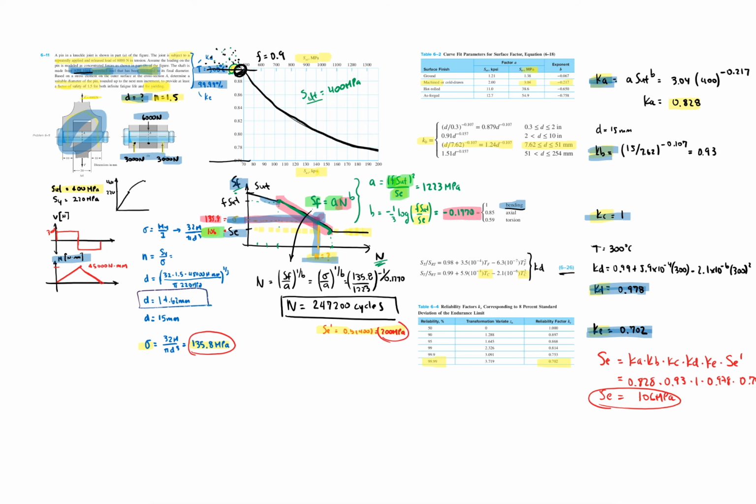Okay, so all of these problems are almost reduced to finding the endurance limit. The ideal endurance limit is just half of the ultimate strength, but we use the Marin coefficients to get a more accurate and more conservative real endurance limit. Okay, and because we know this is a straight line, we use this equation to solve for the number of cycles, or if I know that this part is gonna be in loading and unloading for a specific number of cycles, I could also solve for the fatigue strength and calculate in that case something like the fatigue factor of safety.